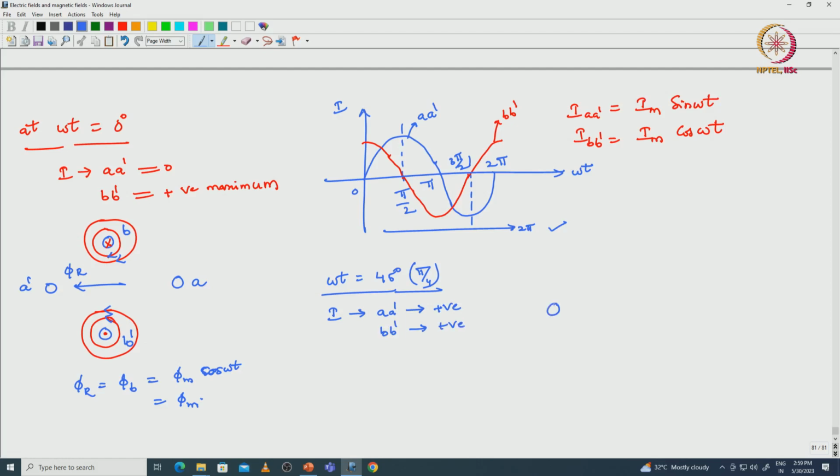So we will see how the magnetic fields form inside the machine through flux loop analysis. This is B and B dash, A and A dash; the current is positive. So here cross and here also cross at the A and B terminals, and at the A dash and B dash terminals it is dot, as current is coming out.